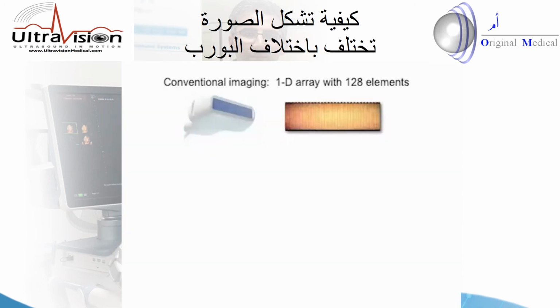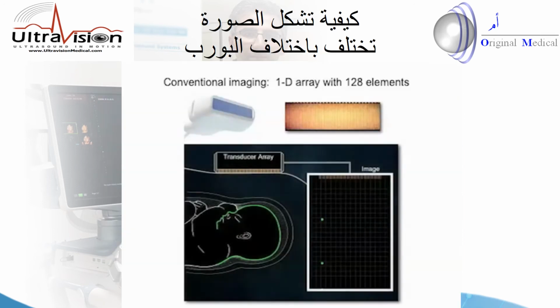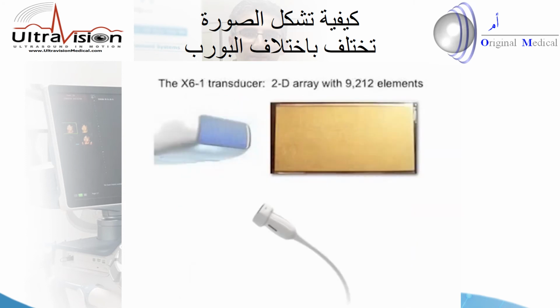A conventional transducer has a number of elements aligned in a row, and these elements are excited in groups and echoes detected one at a time to form the lines of an image, perhaps 100 or 200 lines that make up a B-mode image. The plane of this image is defined by the direction that the transducer is pointing in, and if we want to change that plane, we have to move the transducer either with our hand or with a motor in some transducer probes.